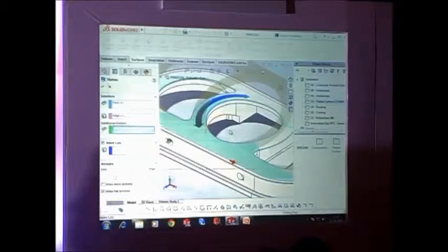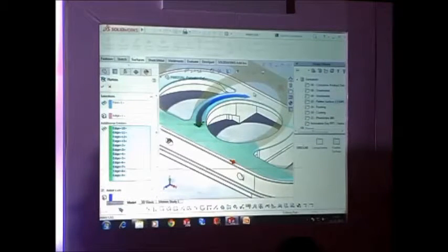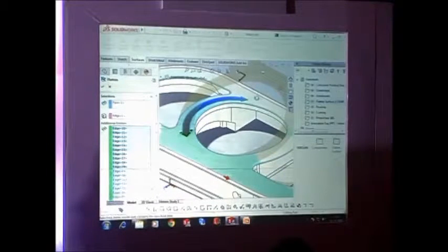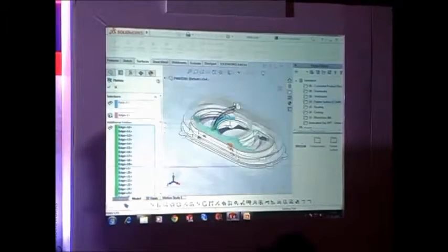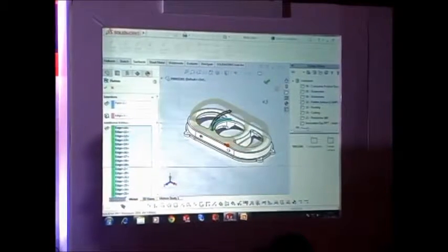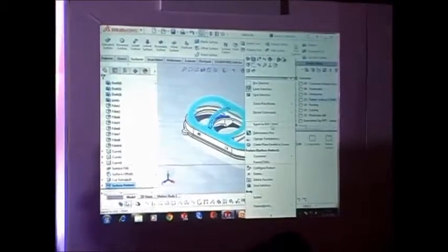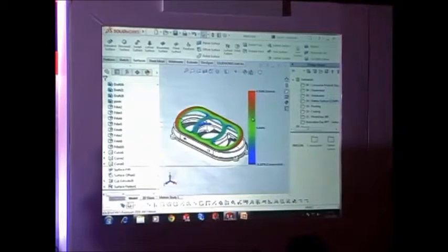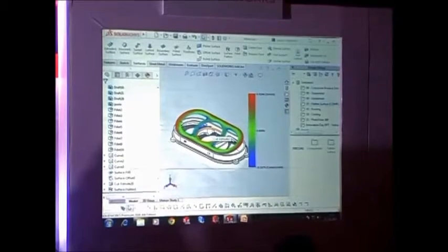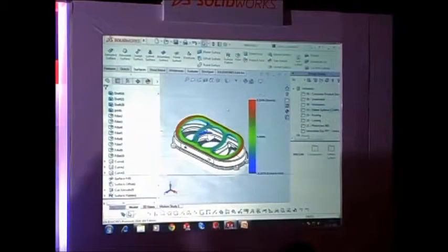Not only that, we can also add additional entities onto our flattened surfaces, which helps manufacturers form the surface. A common challenge faced by industry personnel is identifying the induced stress on the flattened surfaces. This can be easily found using SOLIDWORKS deformation plots. Even if the size of a component is modified, you can easily get an accurate result of the stretch and compression here.